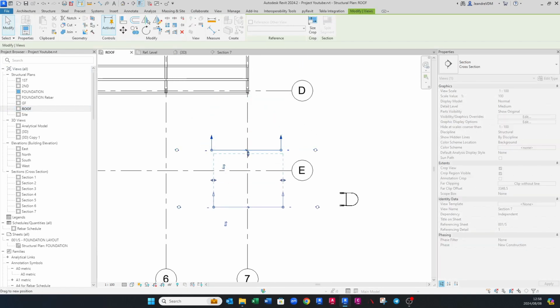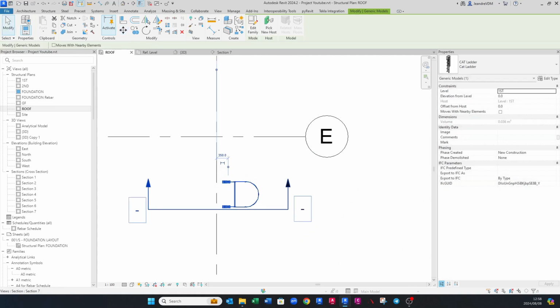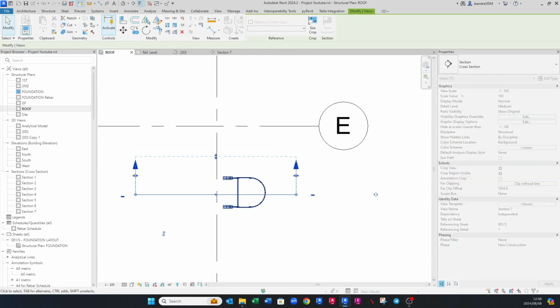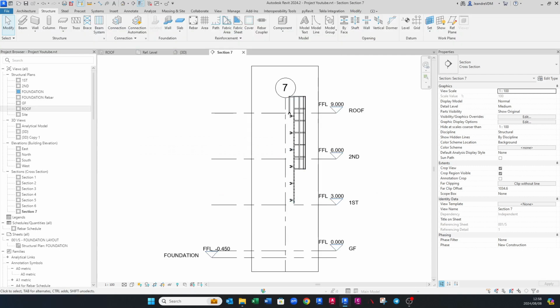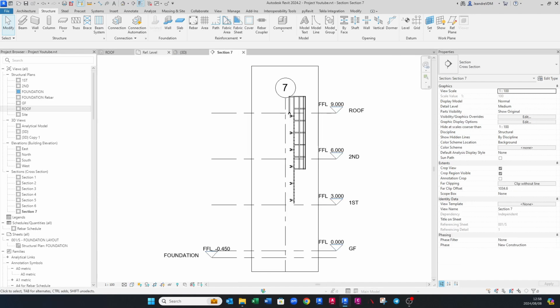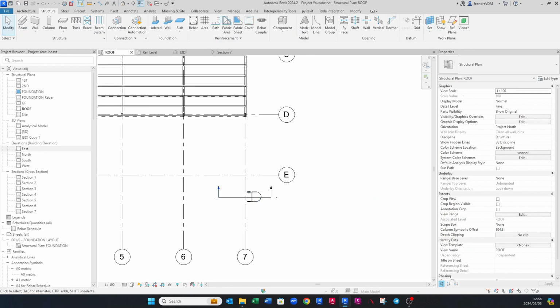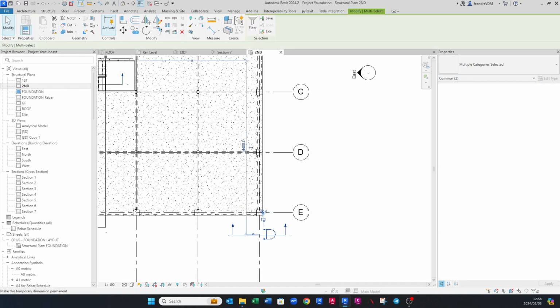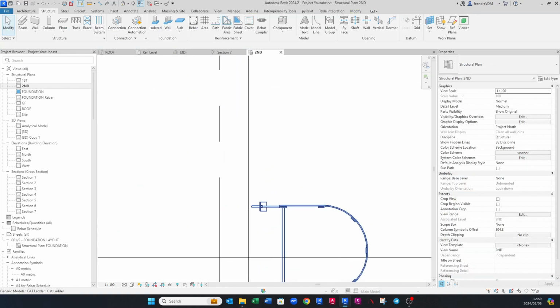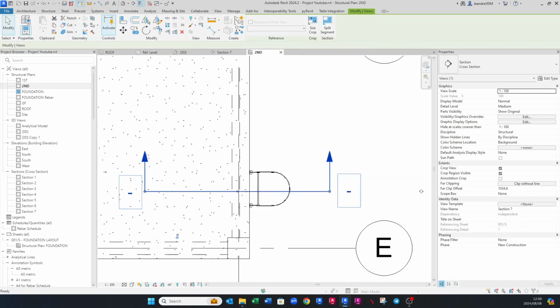Let's move this section indicator here, and move this towards here, so we can see, we draw section 3 here, how it's going to look and how we can adjust that. I actually must place it more upwards so it sits within our wall. If I go to the second floor, you can see the slab. There we go. Let's move that up. I'm going to align it here on the edge. There we go.